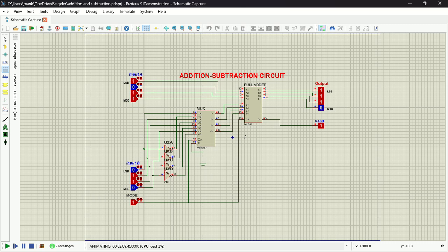When it's addition, nothing much really happens, because if you set the mode to 0, that means we have no carry input. We also simply select B, and we just compute the sum of A and B to get our answer. That is basically how this circuit works.